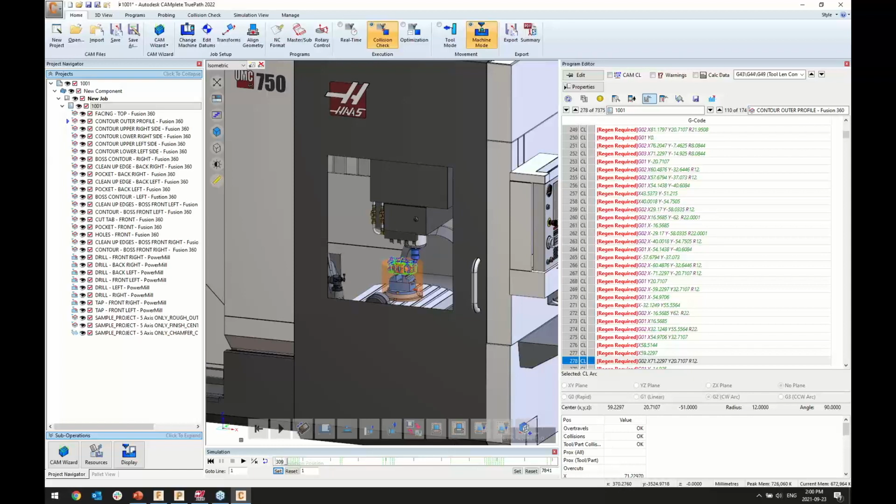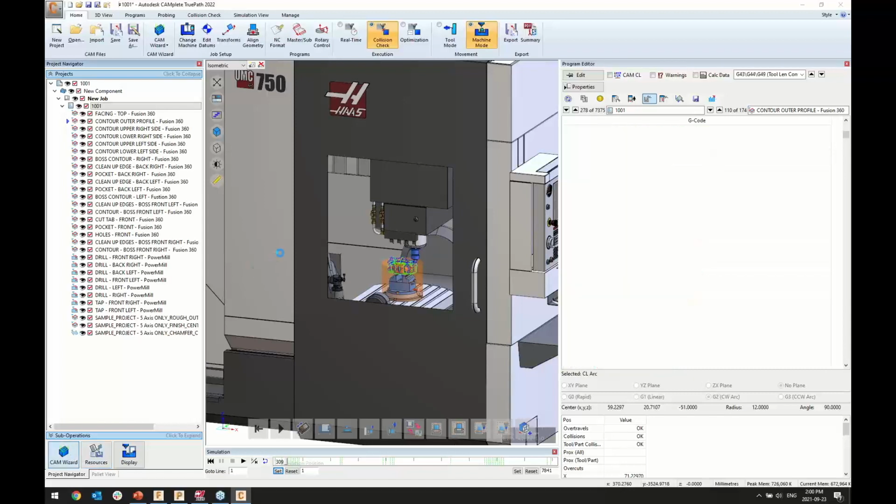Just one thing to note on the export of the models, sometimes in larger platforms like, for example, NX or CATIA, if you're working in an assembly, the parts, when exported, may be exported in the assembly orientation, not necessarily the machining orientation. So again, in TruePath, there are tools in place where we can reorient each element individually, independently of the other element.